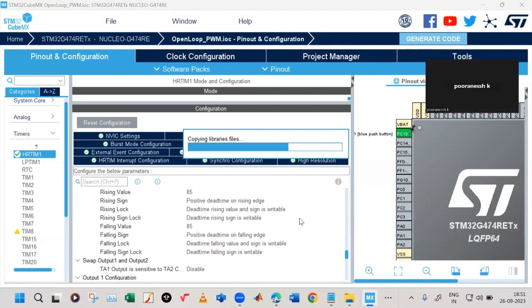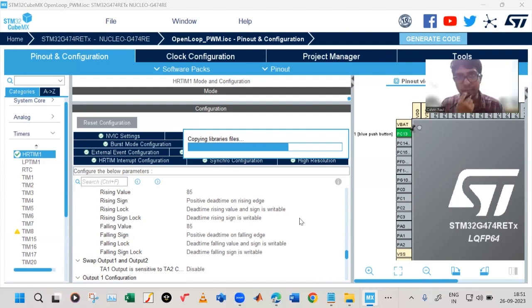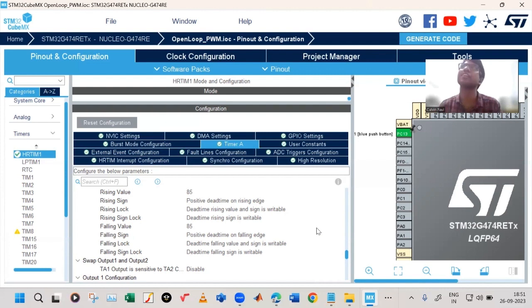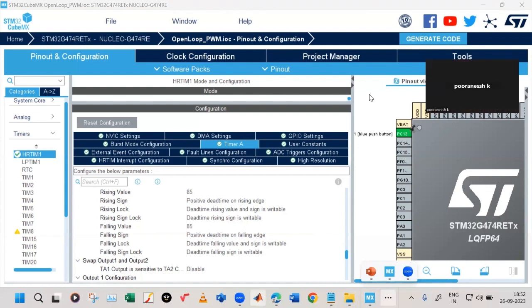Basically, how much percentage of our cycle that time should be? See, dead time is a very tricky thing. You don't want it to be too long, and too short is dangerous. Basically, we give a large value, or if we find that this cross conduction is still happening, then we have to increase the dead time. A trial and error process. There might be some papers on how to actually come up with a good value, but I don't know currently.